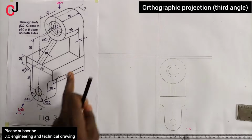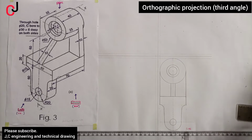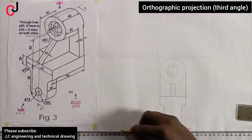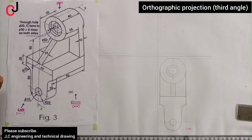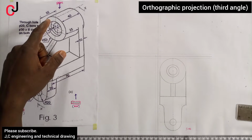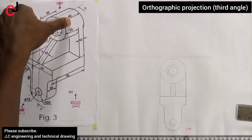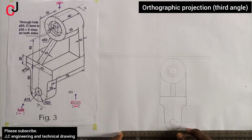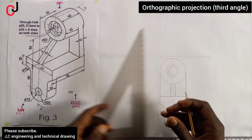And then we'll move to our front view. So what we need to do, from the base of our side view, the total height is still the same. So we'll project to my left. And then from our diagram, we can see that the total length of our side view is 35 plus 40, which is 75 millimeter. So we'll measure 75 millimeter, indicate the point, and then we'll project upward.